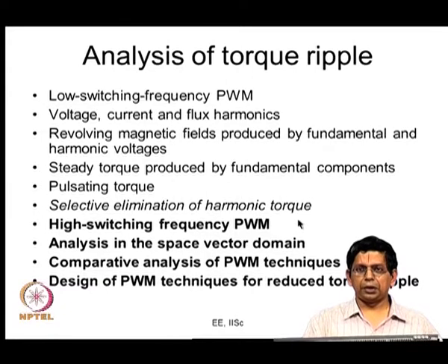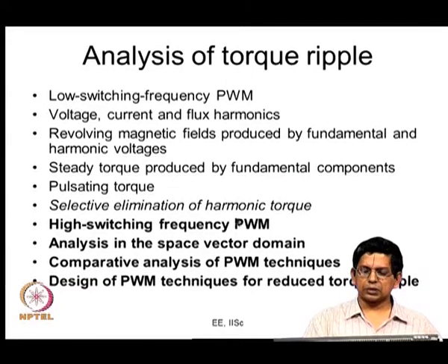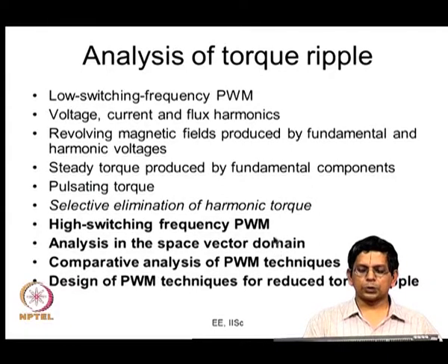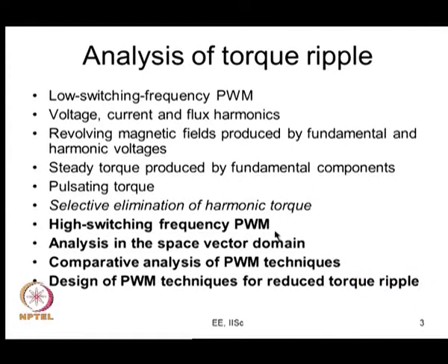So, we would look at this once again today, and then we would move on to what is really the focus for today, that is the high switching frequency PWM. We will look at it from the space vector point of view, because that is more general than the triangle comparison, and we will be dealing with certain space vector based PWM methods which really cannot be implemented in the triangle comparison mode. So, we would look at a few advanced bus clamping PWM schemes too here.